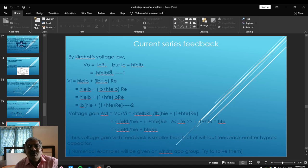We have to take the ratio of output voltage VO upon input voltage VI so as to get the voltage gain after feedback. By putting those values, we can get minus HFE IB RL upon IB into bracket HIE plus 1 plus HFE RE. Naturally, IB will cancel so as to get minus HFE RL upon HIE plus 1 plus HFE RE.